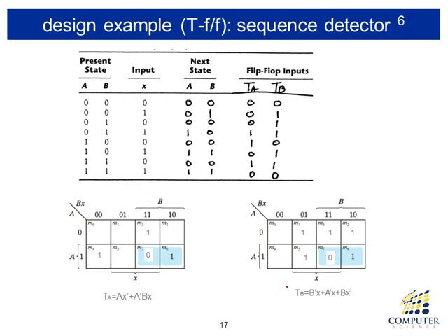The last case is that if you want to use a T flip-flop instead, then similarly we need to extend the state table. Given the state table, we are going to use T flip-flops for A and B. Similar to the JK flip-flop, currently flip-flop A has 0 and the future value on the next clock is 0.